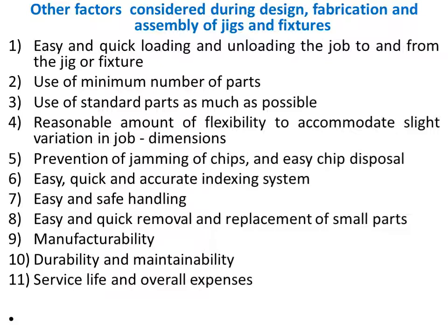During cutting, the chip should not get clogged inside the fixture, and we should be able to remove the chips very easily from inside the fixture. Then an easy, quick and accurate indexing system, where there are certain components which may require indexing like a gear, or you may have to drill holes from various sides, so you may require some kind of indexing incorporated into the fixture.